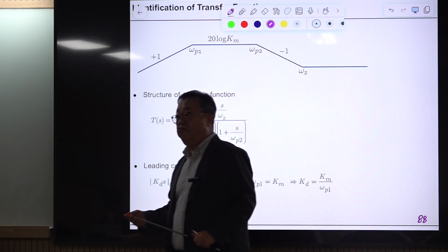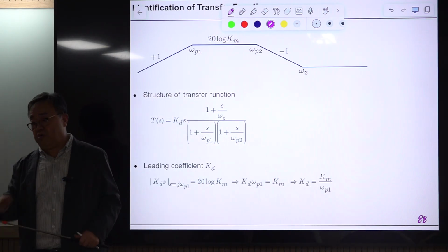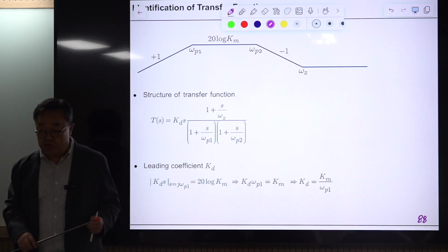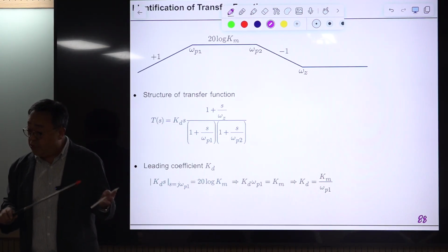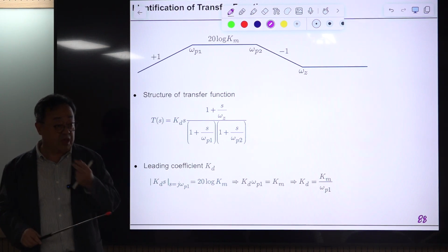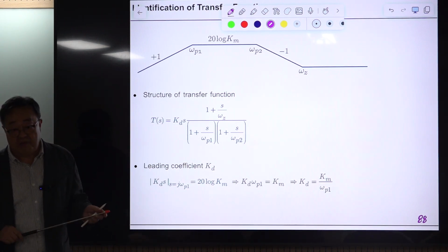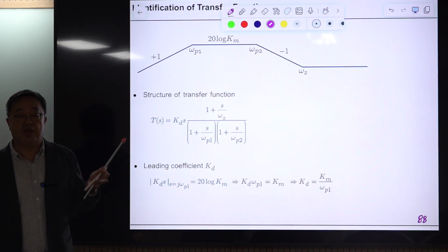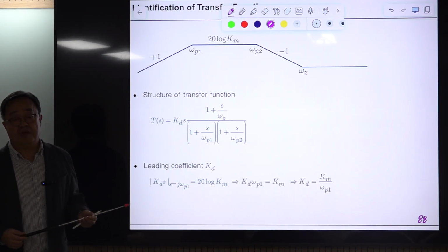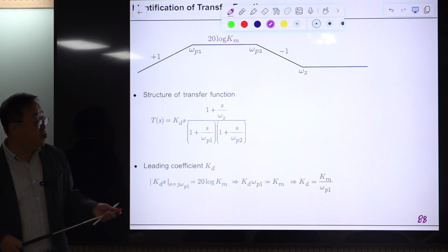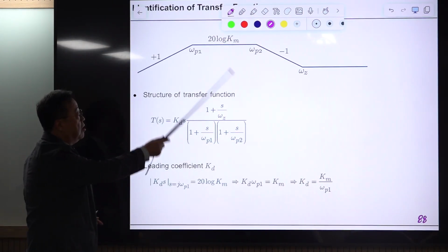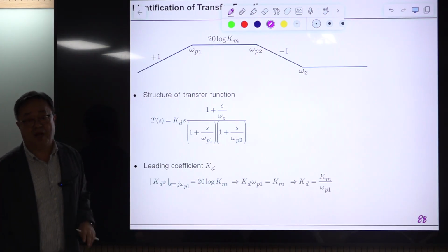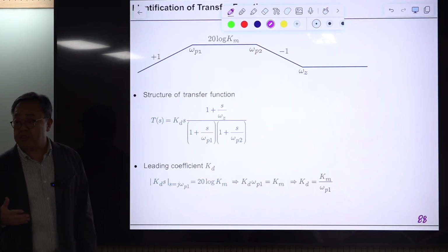Actually, one famous technique of this controller design is the loop gain shaping technique. You will learn the loop gain. Loop gain is the most important quantity in any dynamic system. By shaping the loop gain to the desired form, you can obtain the desired closed-loop performance. For that, you need to use this graphical approach. You will be learning that approach a lot.